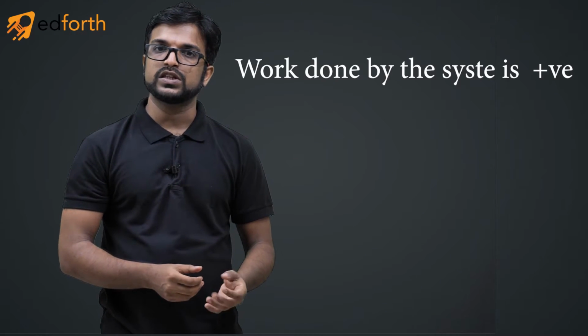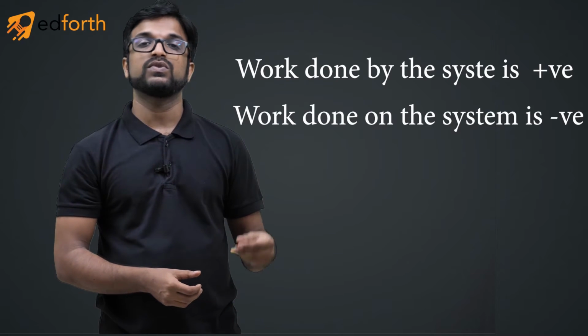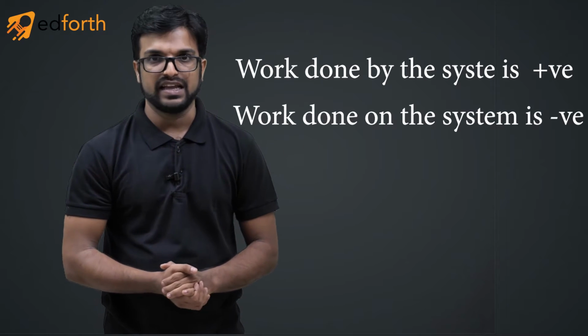Now you know that work transfer can happen from system to surrounding or surrounding to system. If the piston is going up, I will say that work is done by the system against the surrounding. If the piston is going down, that means I am pressing it down, that means the surrounding is doing work on the system. So both have different directions. In order to account for this direction, we will follow a sign convention. Work done by the system will be taken as positive, work done on the system, that means work done by the surrounding, will be taken as negative. Throughout this course, we will be following this sign convention.